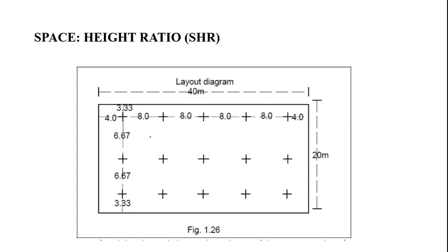If you consider the top view, then each luminaire can be considered as a point source, that is like this, just like this, a plus sign. So it is situated like this. Now the adjacent distance between the luminaires we have calculated, S equal to 8.25 meter. So you have to make sure of this adjacent spacing, 8.25.